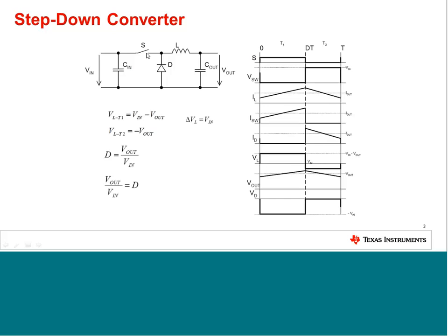When the switch is opened, the current is redirected because the inductor forces it to continue to flow. It is redirected through the diode, and the energy in the inductor is discharged to the output, which you can see with the downslope of the inductor current curve. This is all ideal behavior.